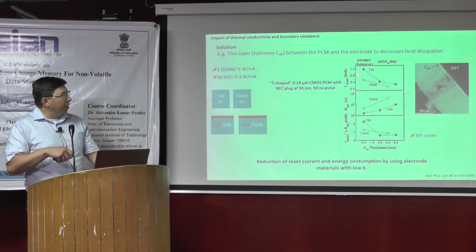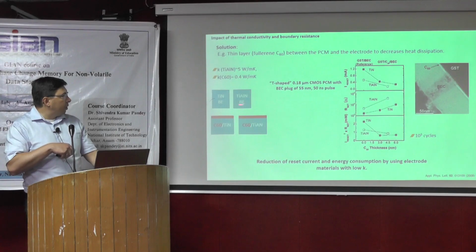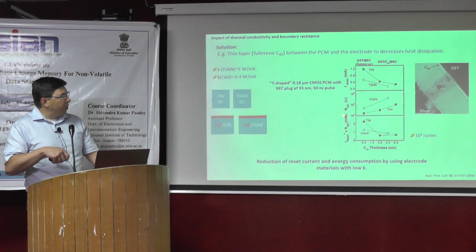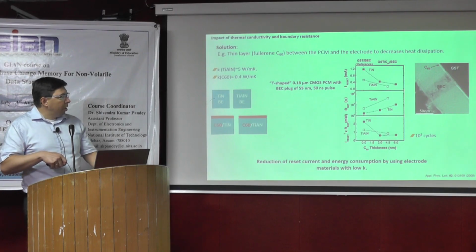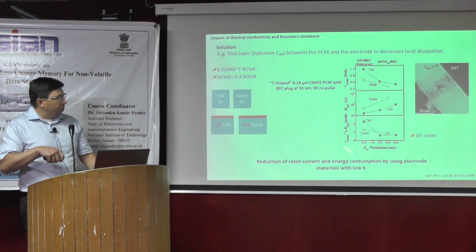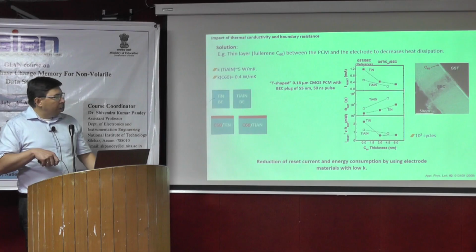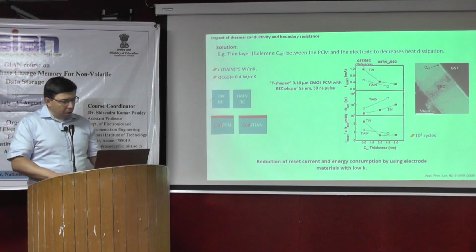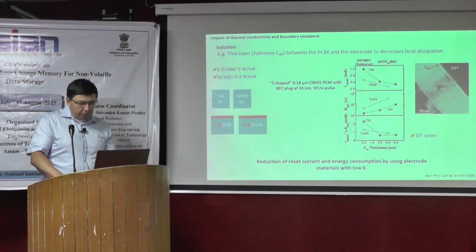We can see the reduction of reset currents for both types of electrodes, titanium nitride and titanium aluminum nitride. We also see the increase of the resistance of crystalline, which is good for reset operation. There is also a reduction of energy consumption. The endurance here is like 10 to the 5 cycles, which maybe can be improved in further research.